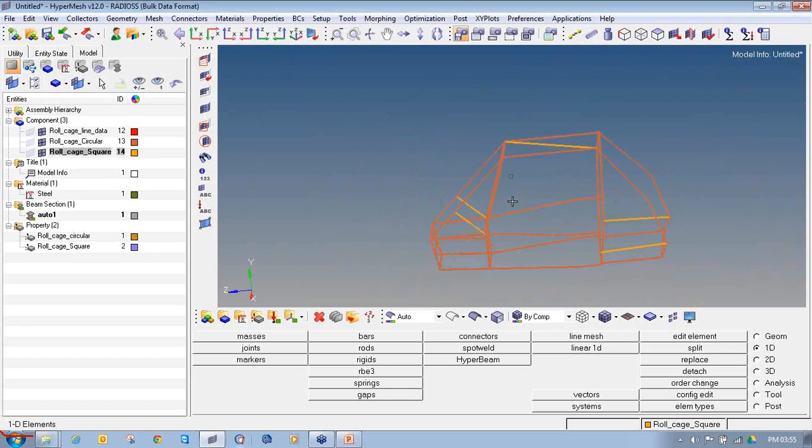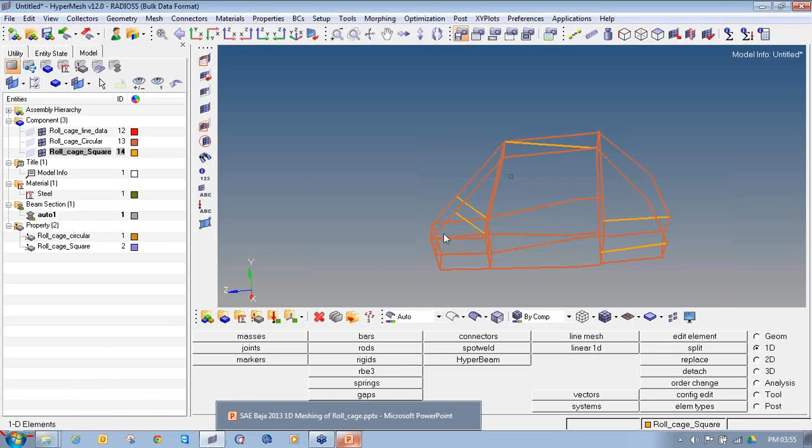The free run stands for we will excite this model in some frequency range and check the connectivity. All the beams should move simultaneously whatsoever the frequency range is. So that is not my point, what the frequency range is. To perform free run, my point is to check the elements' connectivity so that all the elements are connected.